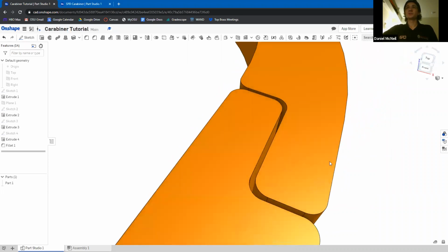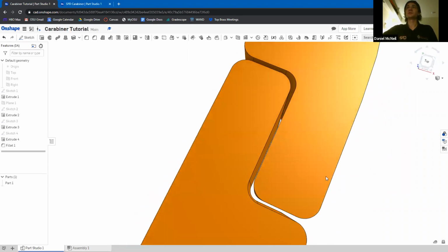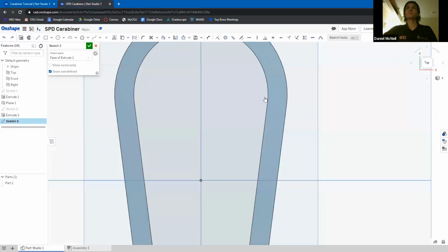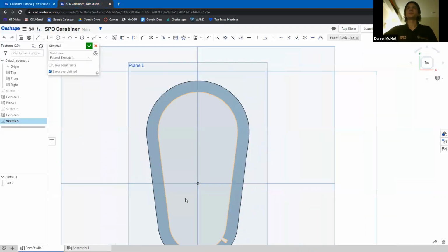To be honest, how we came to the dimensions for this was a little bit of trial and error. The nozzle on the 3D printer is 0.4 millimeters. Based on the nozzle diameter, what type of printer you have, and what resolution you're printing in, you can have either tighter or looser dimensions in order to get this gap to exist. What we don't want to happen is for these two pieces to merge together during the print. So we're going to keep that in mind when we're making this feature.